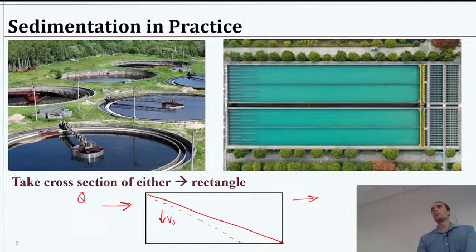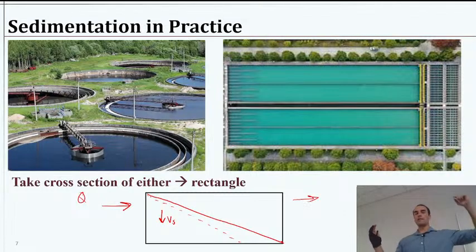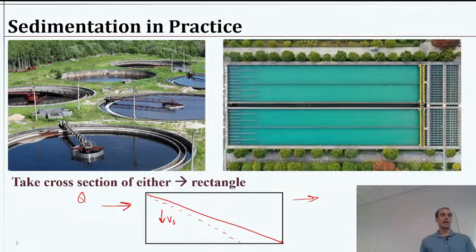So that particle is removed. Anything slower is not. Okay, so we can define something about our sedimentation based on that simple principle. If it reaches the bottom, it's gone, and it's going to do so based on the velocity downwards compared to the sideways velocity through the reactor, right? So it's going to be very simple physics driving this in that sense.